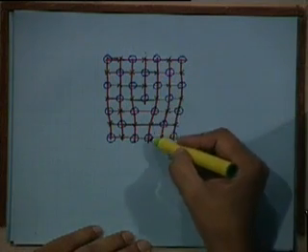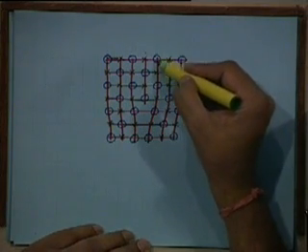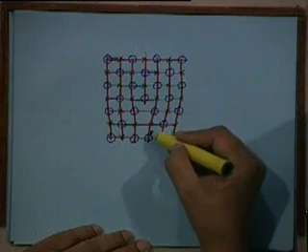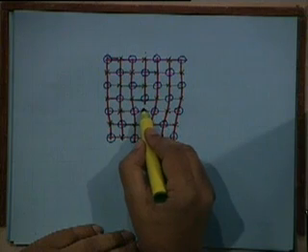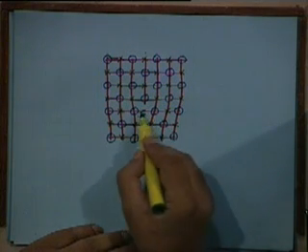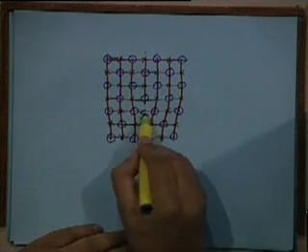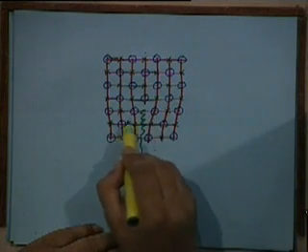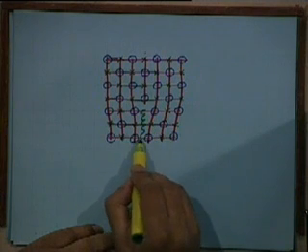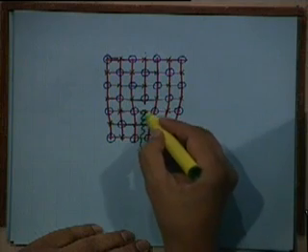This plane is continuing with anion, cation, anion, cation, anion, cation, anion, like that. But see now the situation just below the part plane, somewhere here. This is a little far off because the bond is stretched. These are the two anions coming together, two cations coming together, two anions now coming really together. That's what is making it unstable.